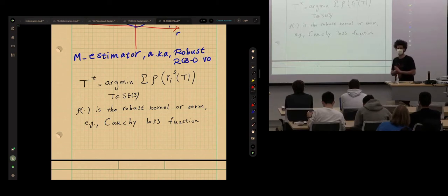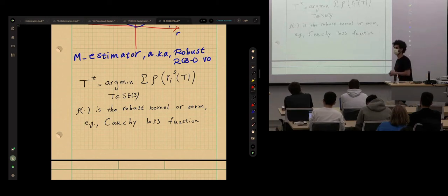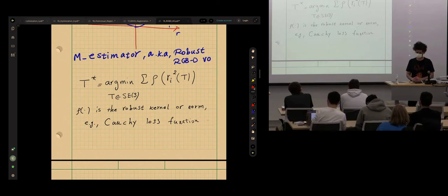Whereas indirect methods can solve that. An example of that system is ORB-SLAM that uses bag of binary words to extract features, detect the loop closure, and then use features and RANSAC to come up with a rough registration of very far frames. And then in the back end, the graph optimization will solve the SLAM problem. Direct methods are not very good at solving that problem.